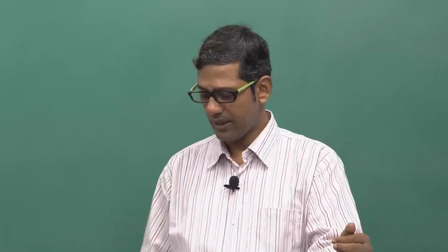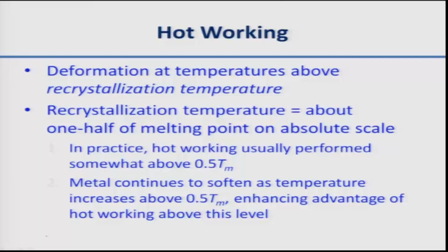So they are annealed subsequently, that means they are heated to a high temperature to remove these stresses, or rather to have a certain kind of equilibrium situation in terms of the defects in the material. Although it is not a true equilibrium, it is some sort of adjustment in the defect structure of the material after the metal forming is done. How this is done? That is the main topic.